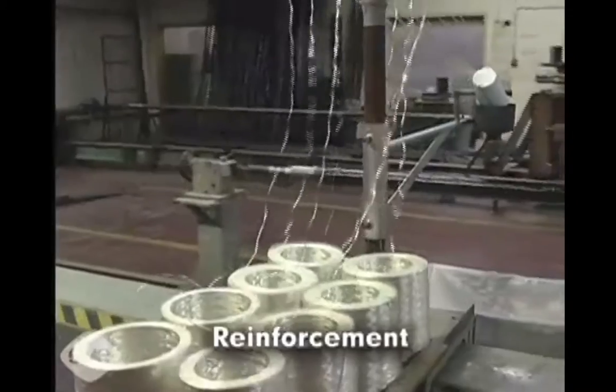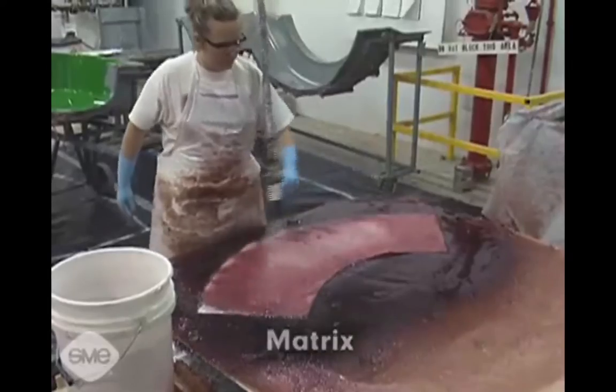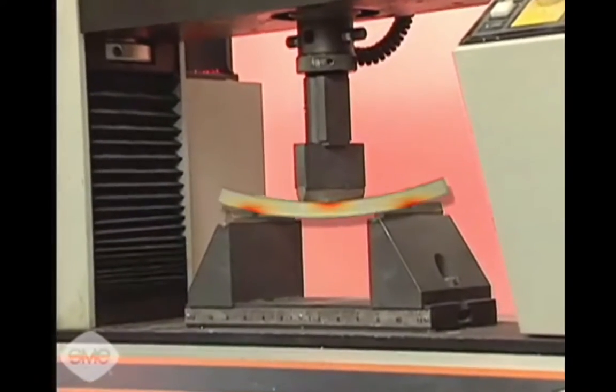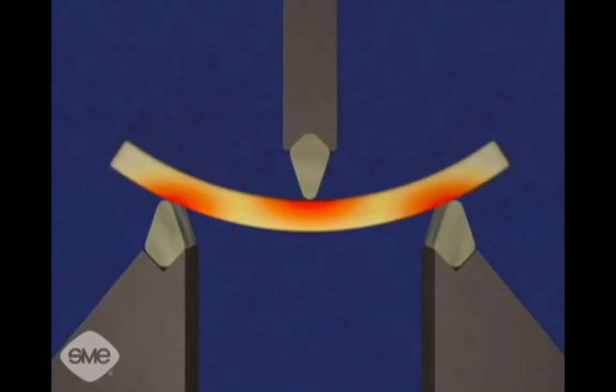and a reinforcement material. The matrix functions as a binder for the reinforcement and controls the physical shape and dimensions of the part. The primary purpose of the matrix is to transfer the load or stress applied to the composite to the reinforcement. The matrix also protects the reinforcement from adverse environmental effects. The reinforcement's function is to improve the mechanical properties of the composite and is typically the main load-bearing element. Reinforcement is usually in the form of fibers or particles.